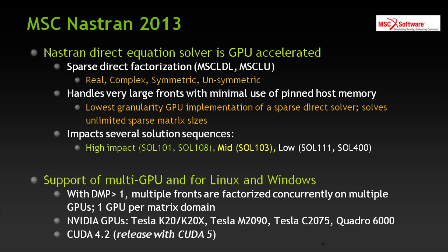Now, I stress again here, the MSC Nastran implementation on GPUs is very unique. For one, it handles very large fronts during the sparse matrix factorization. It's the lowest granularity GPU implementation of a sparse direct solver that can handle very large sparse matrix sizes and is not constrained by the GPU device memory.